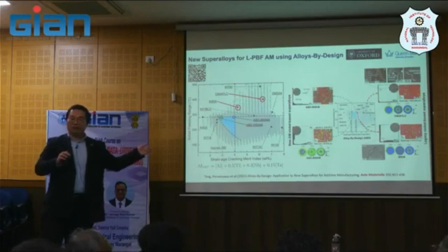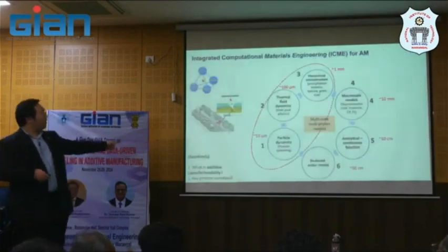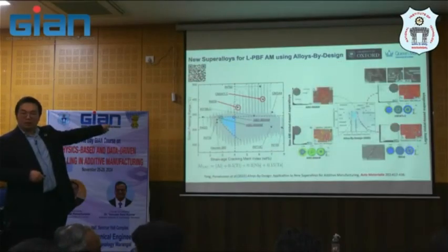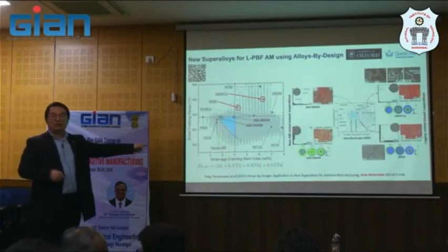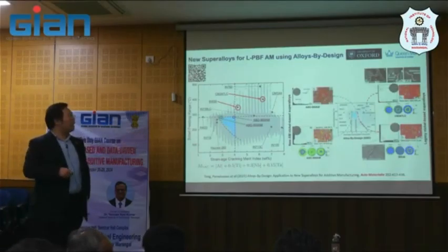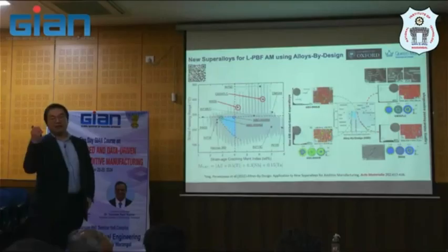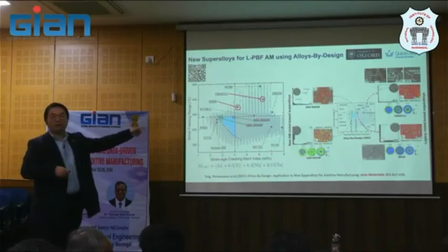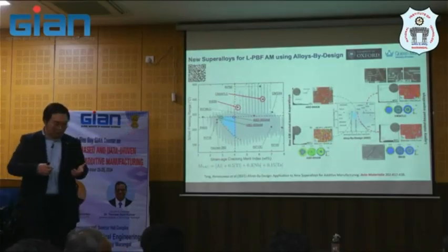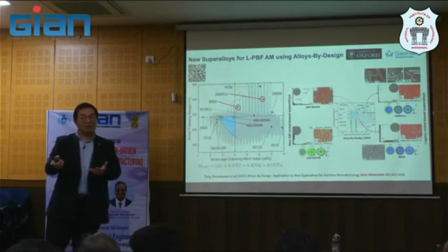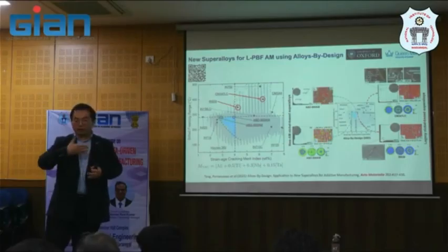That makes sense. This is just about MSc, PhD. This is the same one I showed you in the previous talk, but this is just inspiration. I just want you to be careful that this is just a way to quantify the defect content in the printing, but we call this crack susceptibility. We call all these cracks. But this feature may include liquation, solidification, and something of porosity as well, because once we apply different contrast in the image, this will come up.